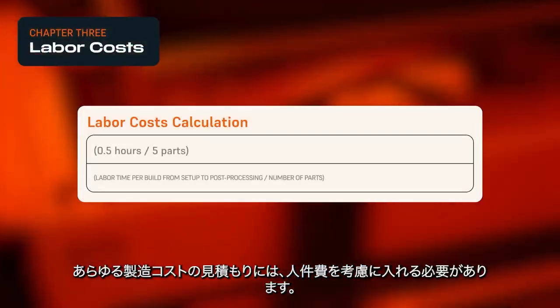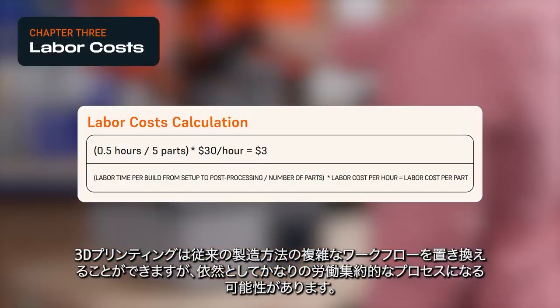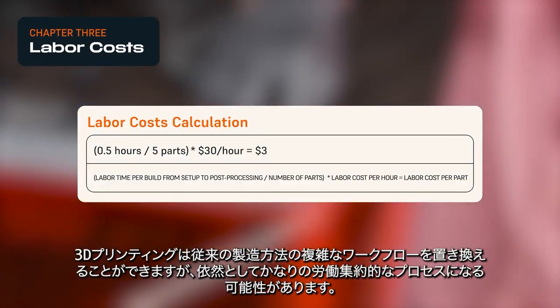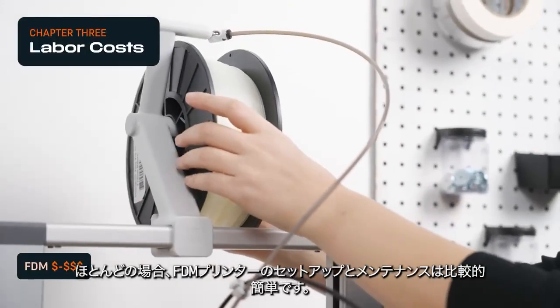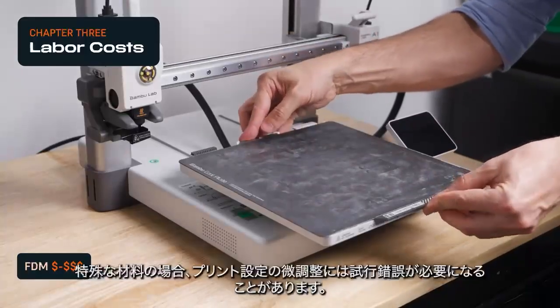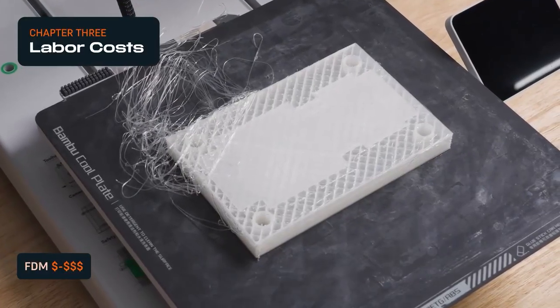Any manufacturing cost estimate must take labor into account. While 3D printing can replace the complex workflows of traditional manufacturing methods, it can still be a fairly labor-intensive process. In most cases, setting up and maintaining FDM printers is fairly easy. For specialty materials, fine-tuning print settings can take trial and error.